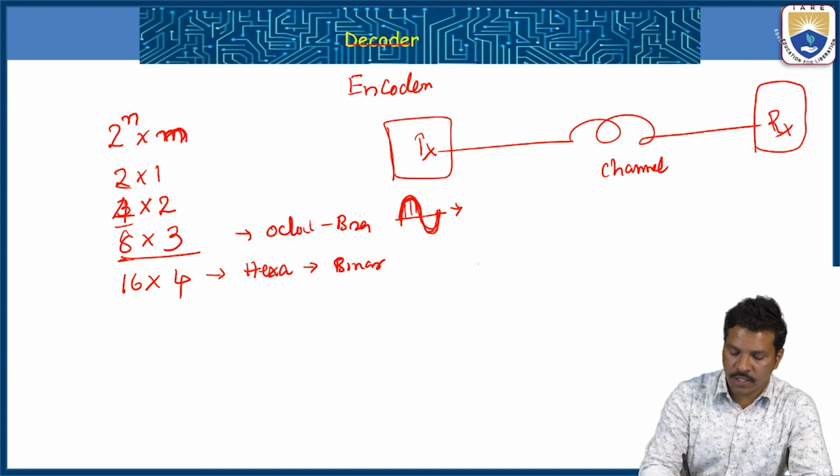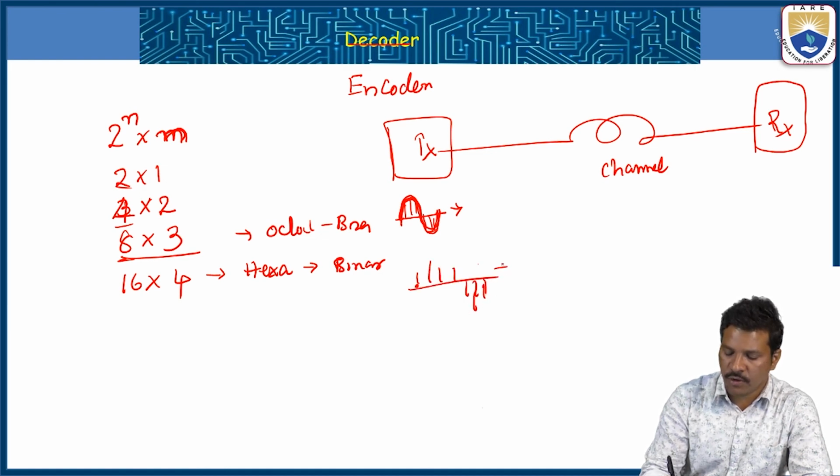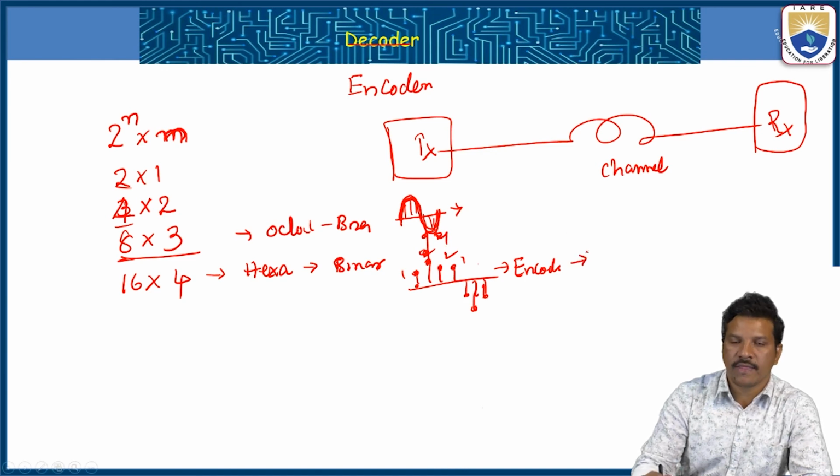If you sample this signal, the amplitude of each sample voltage is represented by a decimal number. Then that decimal signal variation of the samples is given to the encoder, and the corresponding decimal numbers of the samples are converted into a series of binary bits. For example, 4, 2, 1, that one has a corresponding 3-bit representation.